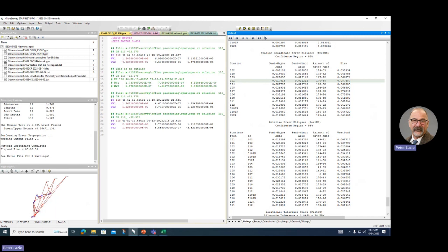I can't say don't do it, but I don't generally play with the centering errors. We had this discussion yesterday and you weren't in on it. When I do GPS, I don't use centering errors. The idea behind it is that for RTK, you repeat at least twice, usually three times.